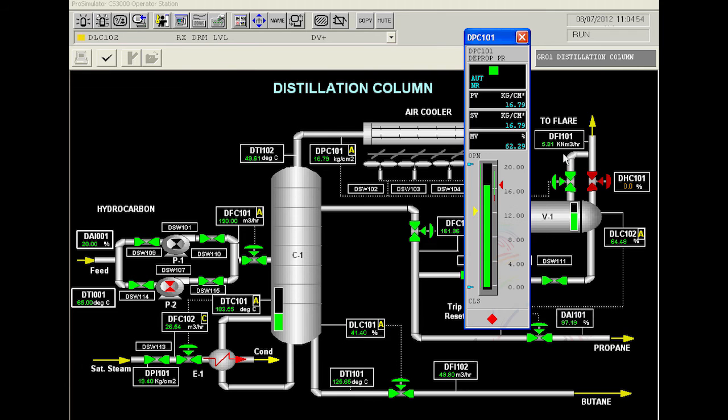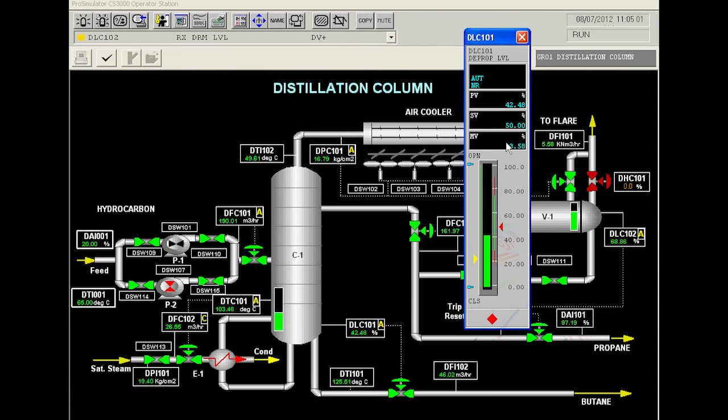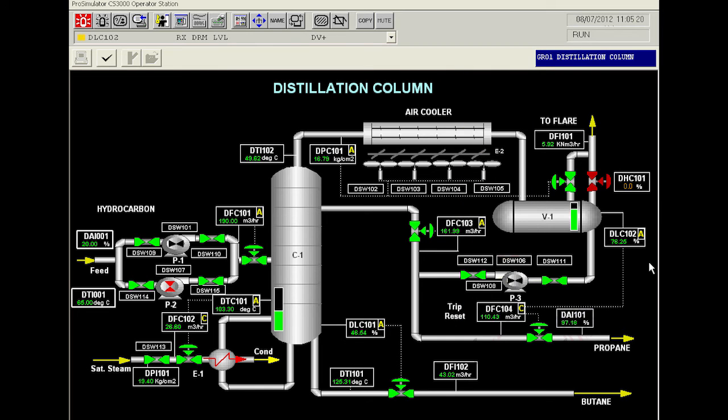The top pressure controller is almost maintaining at the set point. Bottom level has come down. Flow is reduced, and bottom level is trying to get back to set point value of 50%. Top drum level has gone up, and so it has increased the product flow to bring level to set point to compensate for the extra vapor. The level has to change and settle down.